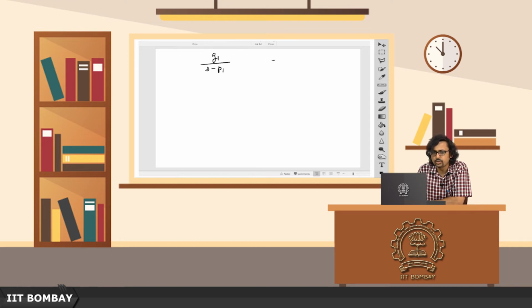I put it to you that you check this block diagram, this sort of a realization for this system. Let's say you have this integrator here, and let's say this is the summer. I know I have represented this sometimes as a cross, sometimes as a plus, it really doesn't matter. As I said, we are only allowed to use summers, gains and integrators. We are only allowed to use op amps in those three forms.